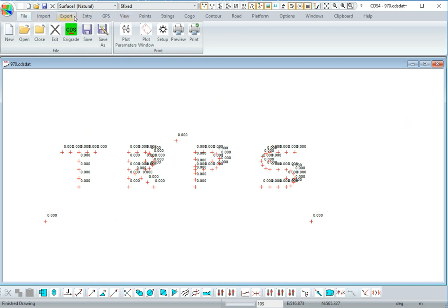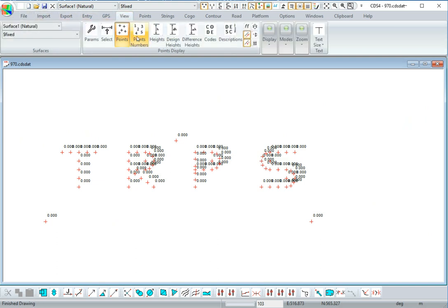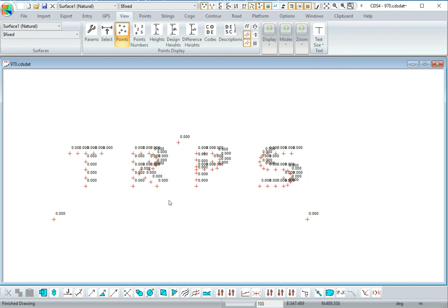There's some other instructions under the View menu. Click on View and look under Zoom. So go into Zoom a window. We left click there. Then we'll move to the screen. Left click on the Zoom window. Then left click on the screen. Keep your mouse button depressed, and then move the mouse, and you'll get a little window.